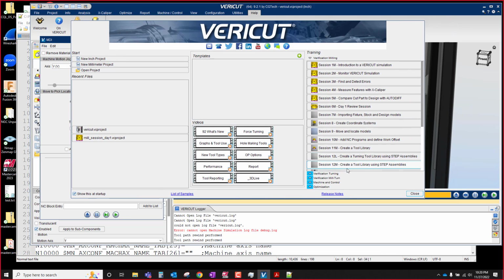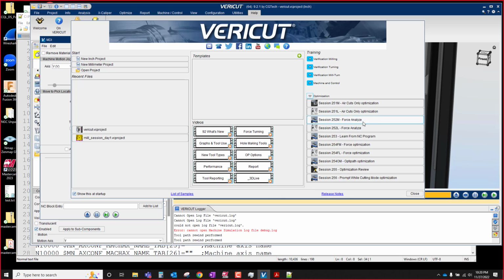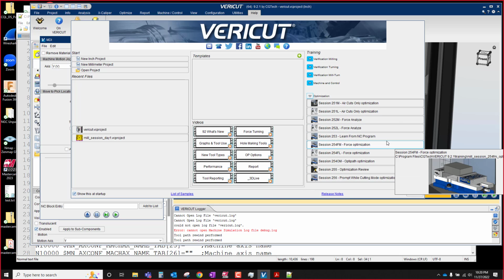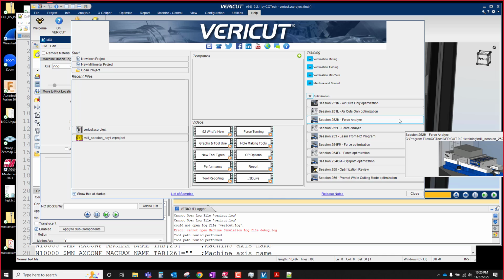The chip thickness graphing is so neat to see, because it's something you don't see with your regular Verify in Mastercam. You know what you programmed the OptiRough to be set at, but every now and then certain things happen, even the OptiRough, or Mastercam, doesn't really consider collisions. Like your back feed rates going over a chunk from your high feed mill at 300 inches a minute or 500, and those little scallops left on the floor from high feed mill operations.